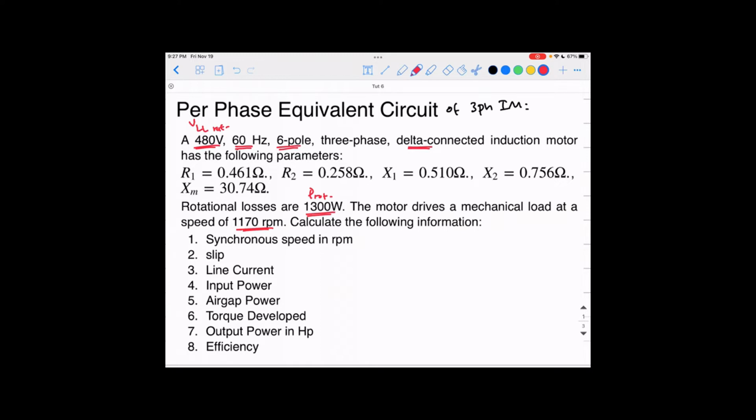So the motor produces as much mechanical power as the load requires, and produces as much torque as the load requires, and the load controls the speed, because the higher the load, the lower the speed. So all those can be something that tells you information about the load, but you have to have any one of those. If it's missing at all, you don't have anything to tell you anything about the load.